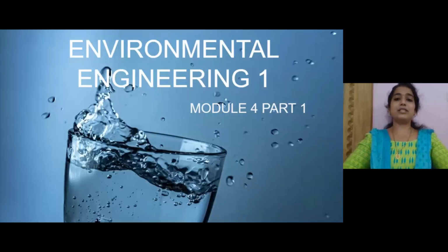Why is this filtration needed in the water treatment system? In the previous treatment, that is in the sedimentation or sedimentation cum coagulation treatment, the flocs are formed in the flocculation chamber by adding coagulants. In the settling tank, these flocs are assumed to be settled down, and this is removed through the drainage system.